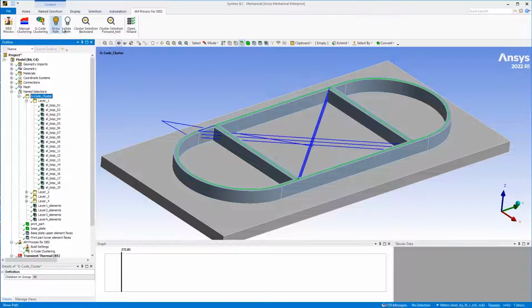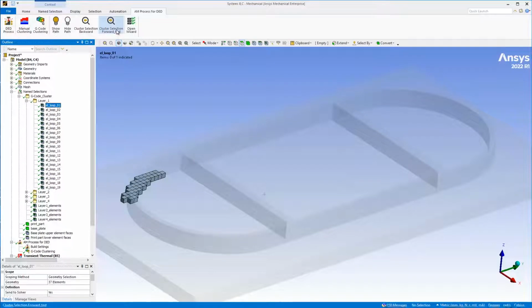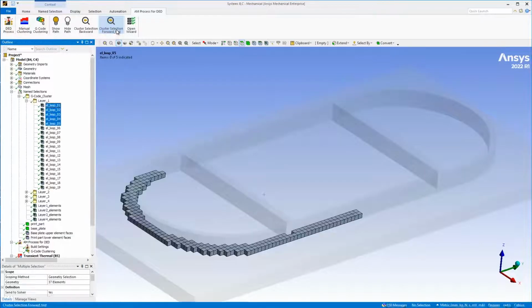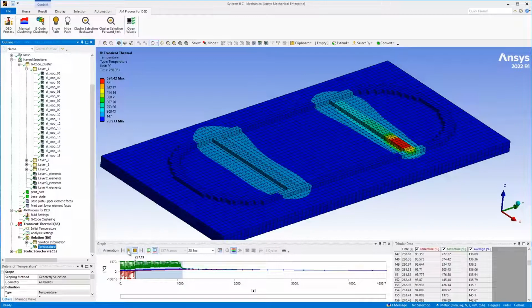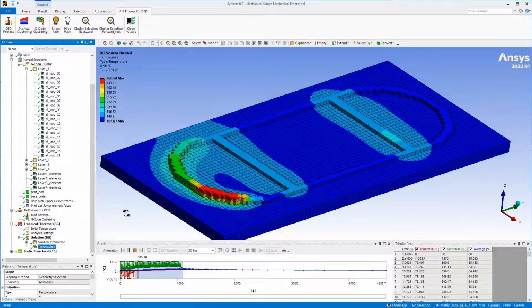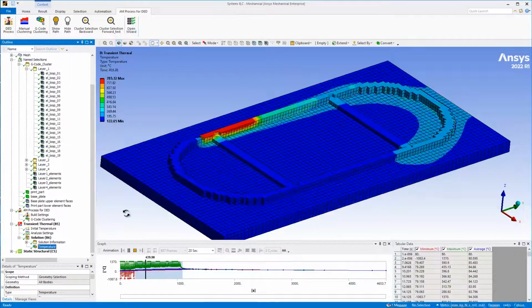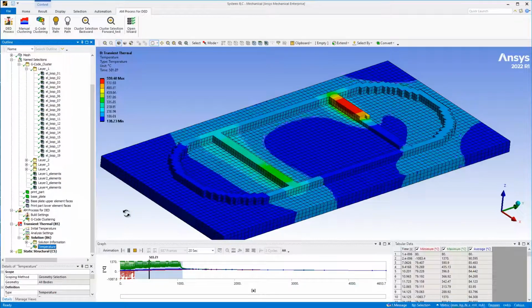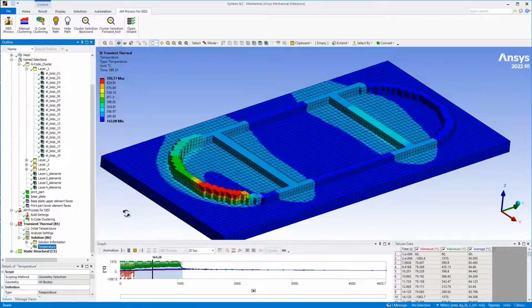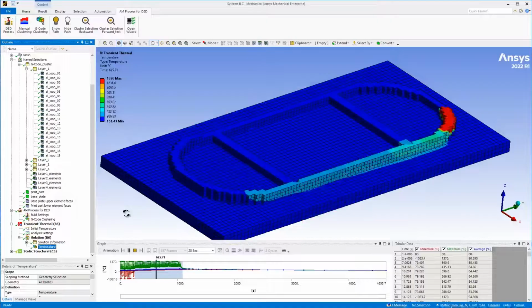In Ansys Mechanical, you can define the 3D printing tool path directly using a G-code machine file or manually using name selections. The simulation uses a birth and death technique of element clusters to follow the tool path and simulation of the welding process. You can easily visualize the tool path and the progression of element clusters before solving. Typical results for the thermal structural system include temperature and deformation contours.